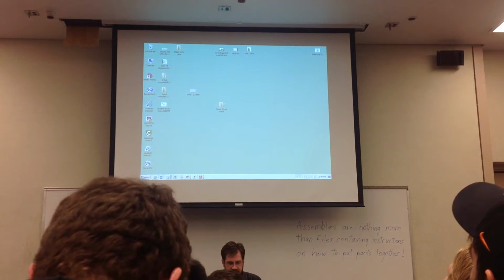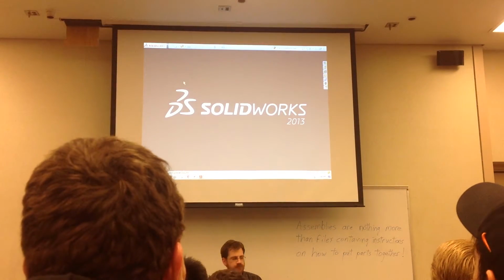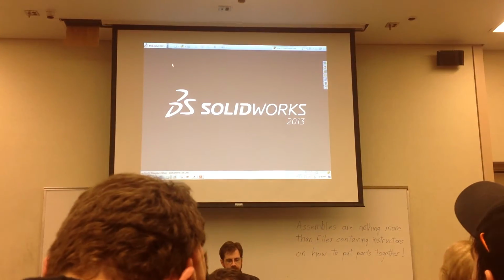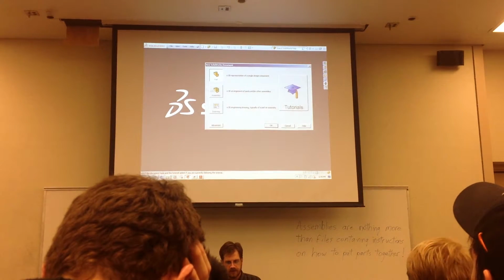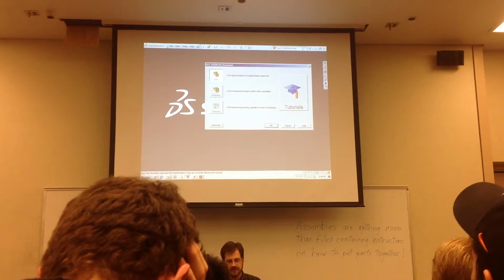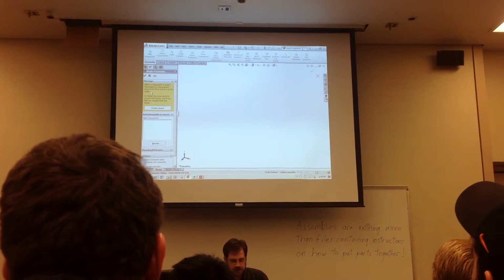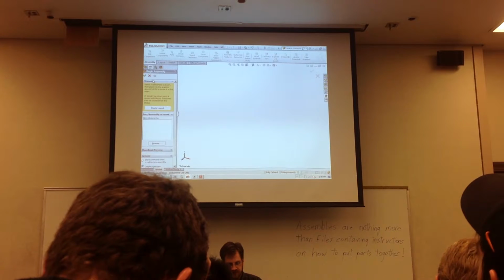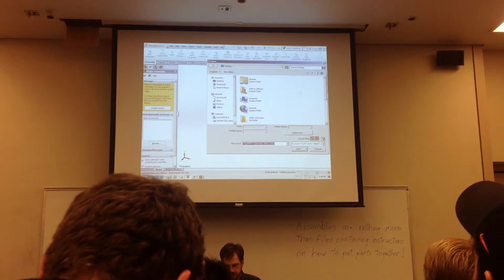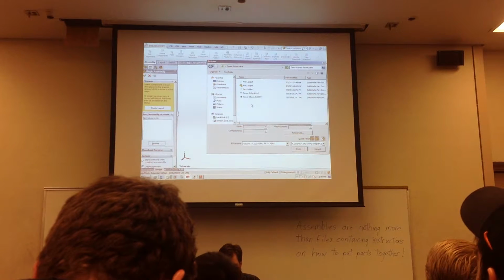Okay, so I've got the uncompressed versions of the files there, and in SOLIDWORKS we're ready now to start a new assembly. So we go to File, New, and for the first time we're going to choose an assembly document. Say OK. And SOLIDWORKS opens up ready for you to bring the first component into your assembly. So you just browse for it. I'll find that folder with my parts, "space over parts".